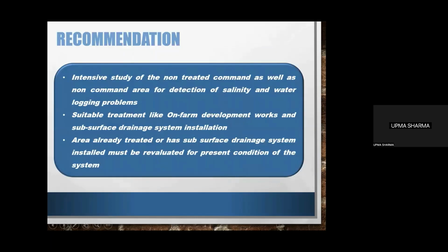Now, what I recommend is an intensive study of the non-treated command area as well as non-command area, because I have found several complaints from non-command areas also, that salinity and waterlogging is causing water to collect in their fields, and due to the saline conditions, their crop production has decreased.